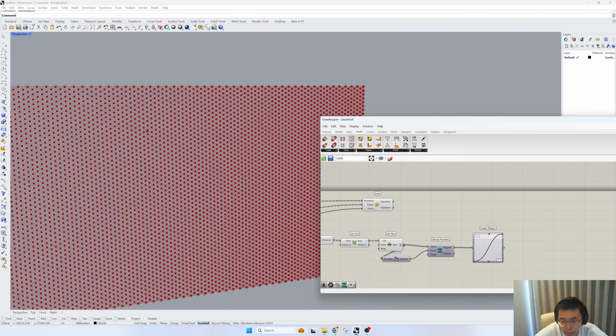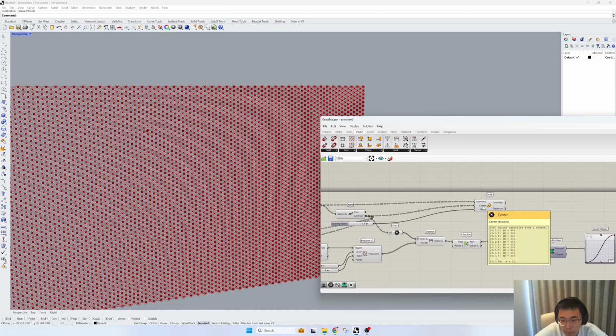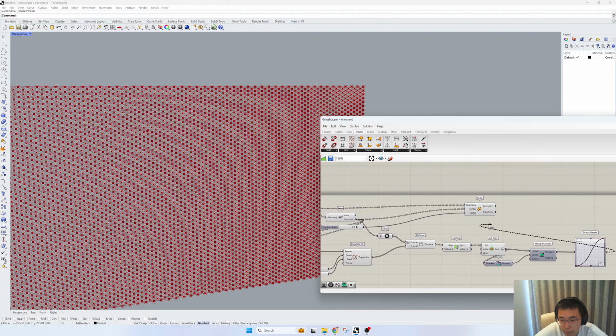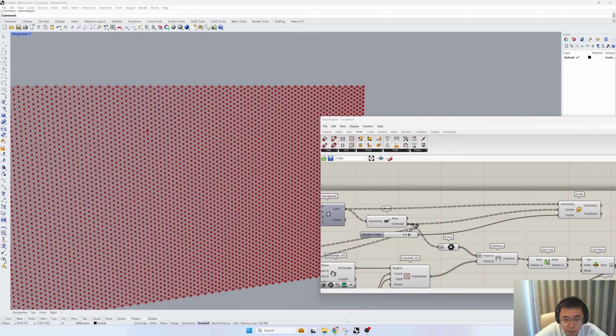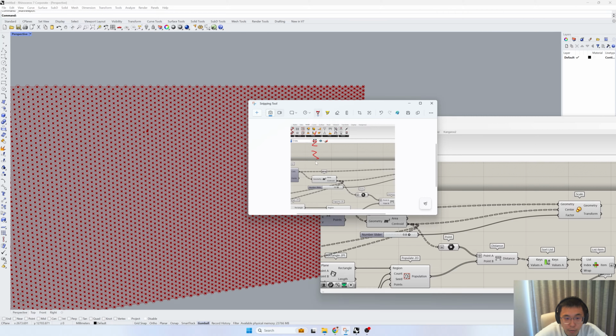And now we have 5,000 numbers. Be careful, but before we just connect it back here, we need to flatten all these inputs again, because that input is a tree. So when you use a tree, for example, we have a 5-number tree and then another 5-number tree. That's our tree, right? So each branch has one number, and when we multiply this tree by that tree, the way it works is 1 to 1, 2 by 2, 3 by 3. So it only works 5 times.